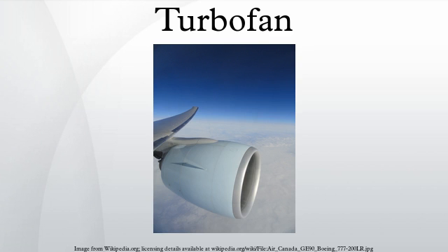Relatively cool air is bled from the compression system, bypassing the combustion process, and enters the hollow blade or vane. The gas temperature can therefore be even higher than the melting temperature of the blade. After picking up heat from the blade or vane, the cooling air is dumped into the main gas stream. If the local gas temperatures are low enough, downstream blades and vanes are uncooled and not adversely affected.